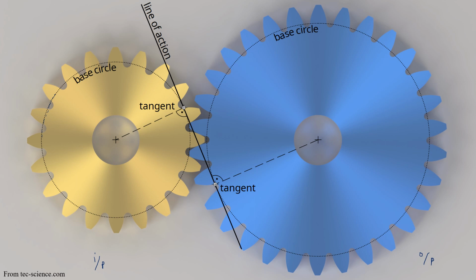And in order to understand the involute profile that I've previously mentioned, you can assume that the involute profile is going to start from the base circle, somewhere from the base circle. And this profile over here is the profile which was illustrated in the previous diagram by unwrapping the fixed string wrapped